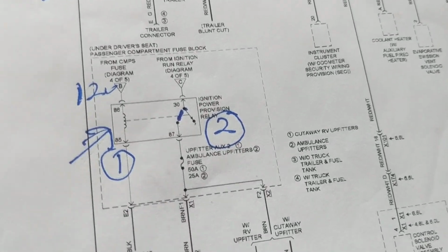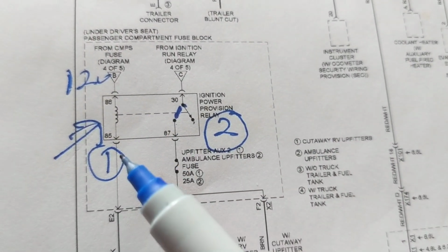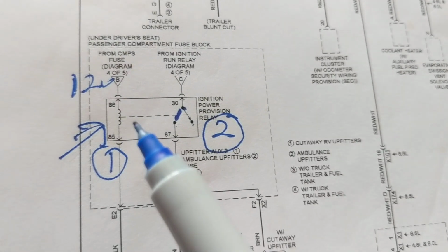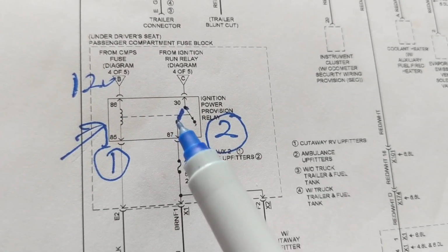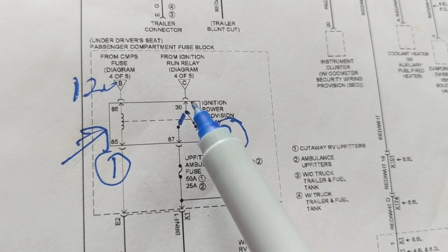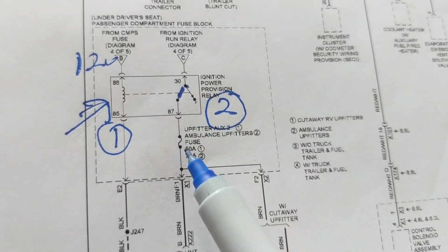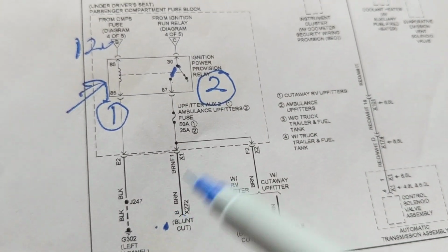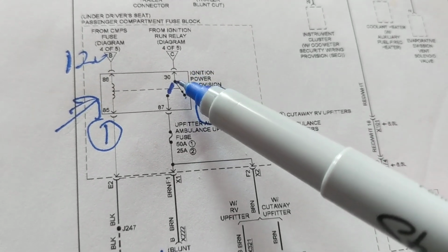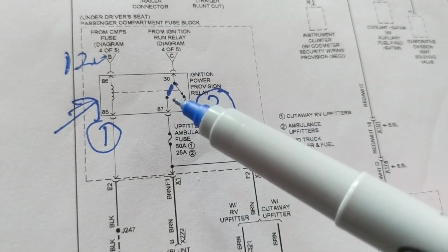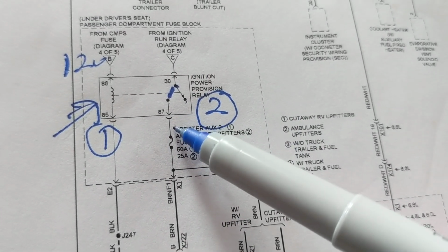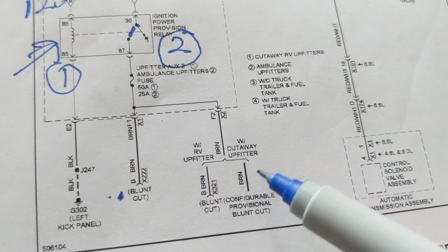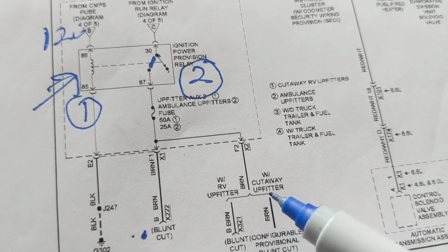All the relays in the relay box are labeled with this: 85, 86, 87, 30. And always remember, if you want to remember how it works, look at the dotted line. The dotted line means it is pulling in the contact, the armature, to close this circuit. Current flows here to ground. Then current can flow from terminal 30 to 87, out of terminal 87, through one side of the fuse, come out the other side of the fuse, and then go where it has to go in these paths.